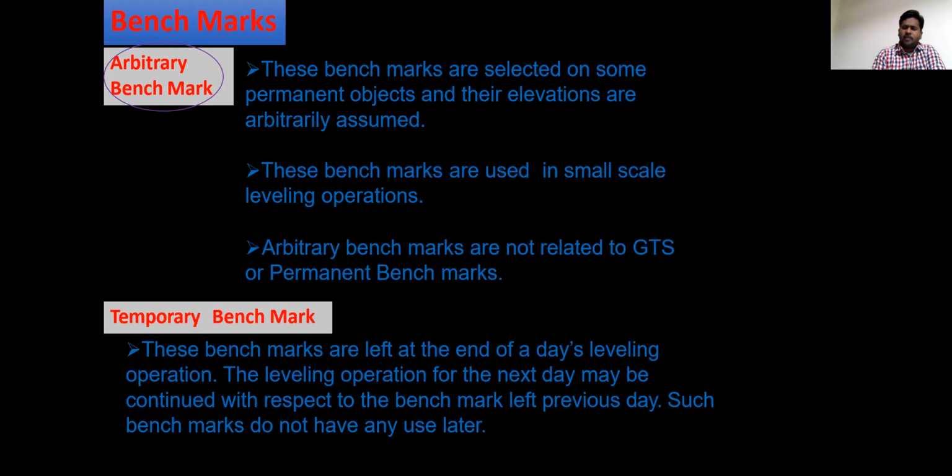Either it may be a building or tower or plant, tree or anything. We assume that for that particular day, not for the whole survey. That is called temporary benchmark. These benchmarks are left at the end of the day's leveling operations.